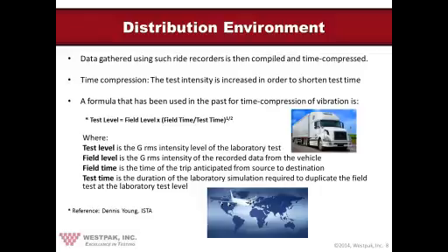If you're doing what we'll call a package performance test, and we'll define that very rigorously in a minute or two, then you should probably rigidly attach it because you're looking for an actual vibration response. Unless a spring mass system, a packaged product in this case, is rigidly attached to the table of a vibration machine, it will in fact bounce because the time compression artificially increases the amplitude, and especially if you're using a random vibration signal, which most people do, you're going to have in excess of 1 G a fair amount of time.